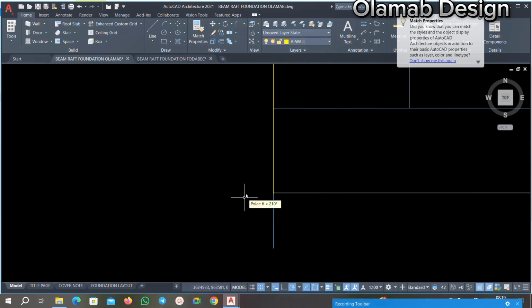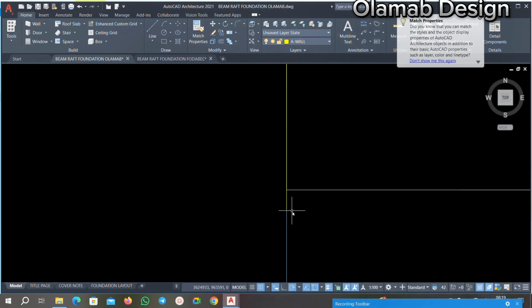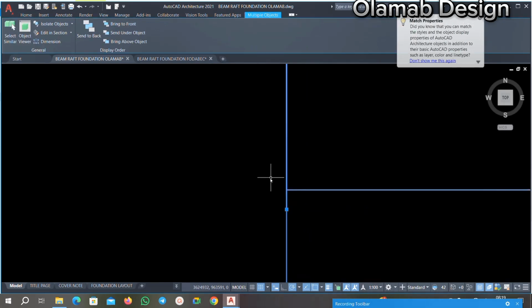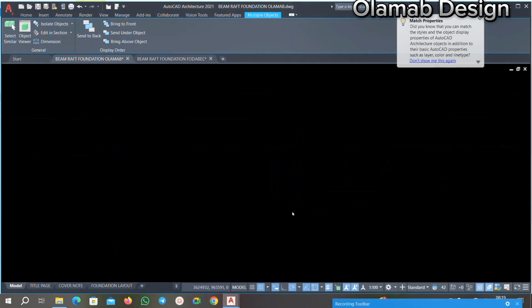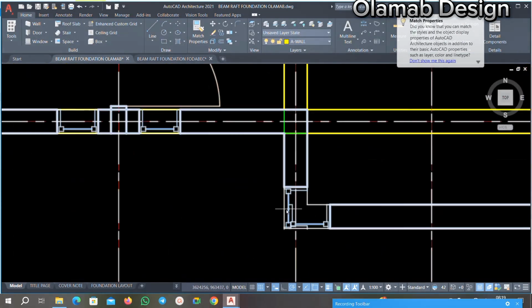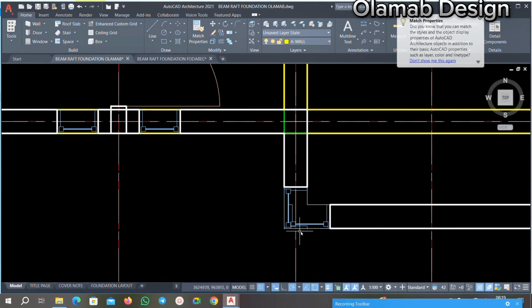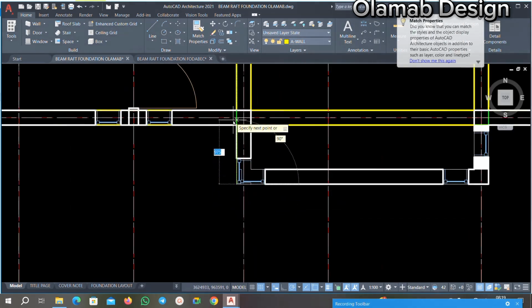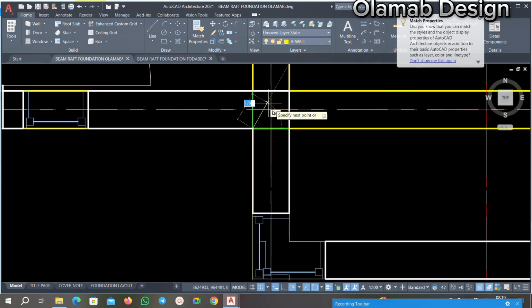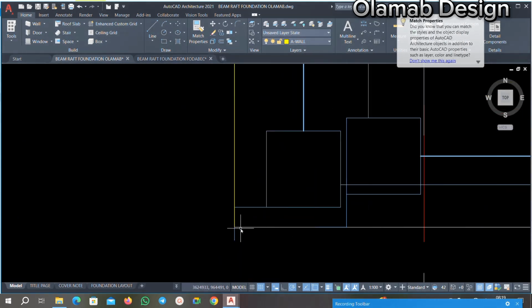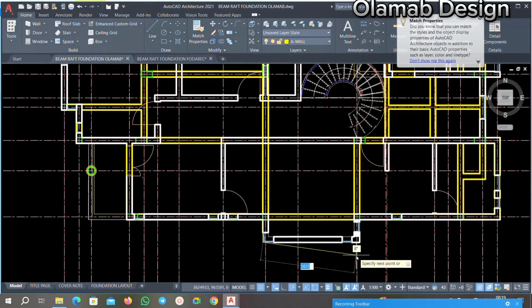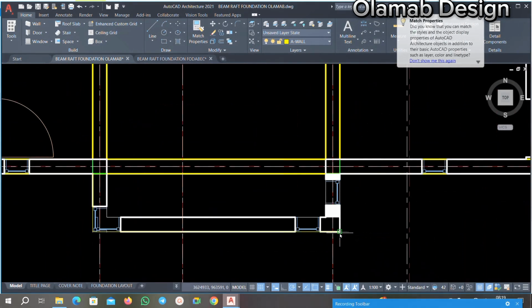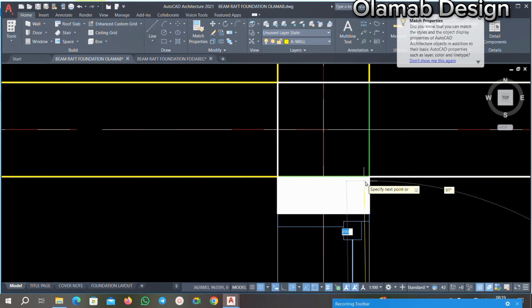Make sure you select the right point. Can you see that this one is even extending more than that point? So you select the line back and delete it, then you select your line, make sure it snaps to the right position, to this point and to this point. If you zoom closer, you see that this line is stopping right there. You click on your line, you take it from this point and you take it to this side and you connect it to the ground floor.